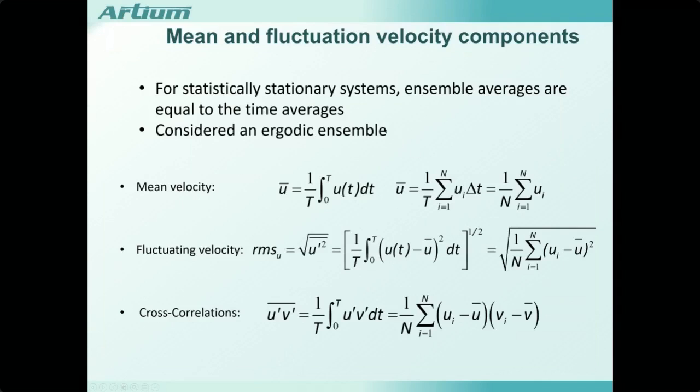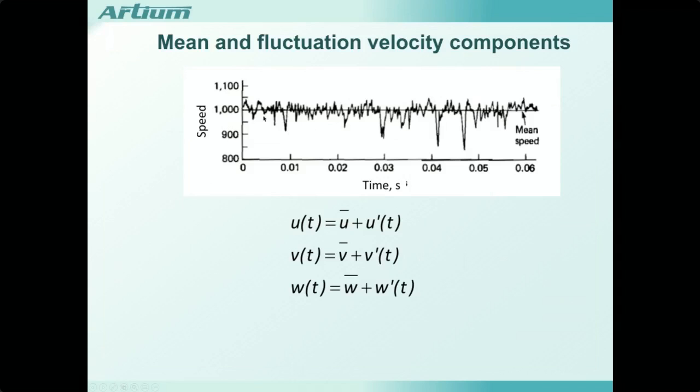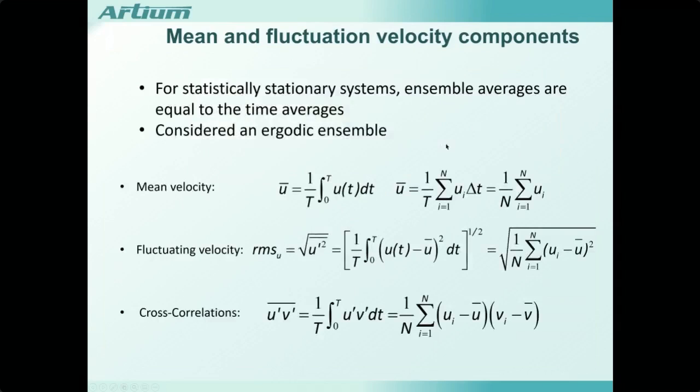With the LDV method, you're discretizing the record, so you're actually sampling at random, albeit very short intervals. You're getting samples as each particle arrives, and if you have a high seeding rate, you're going to discretize. It's a difficult word to say. We're going to discretize the results and form a pattern which simulates the continuous velocity fluctuations, but it's not identical.